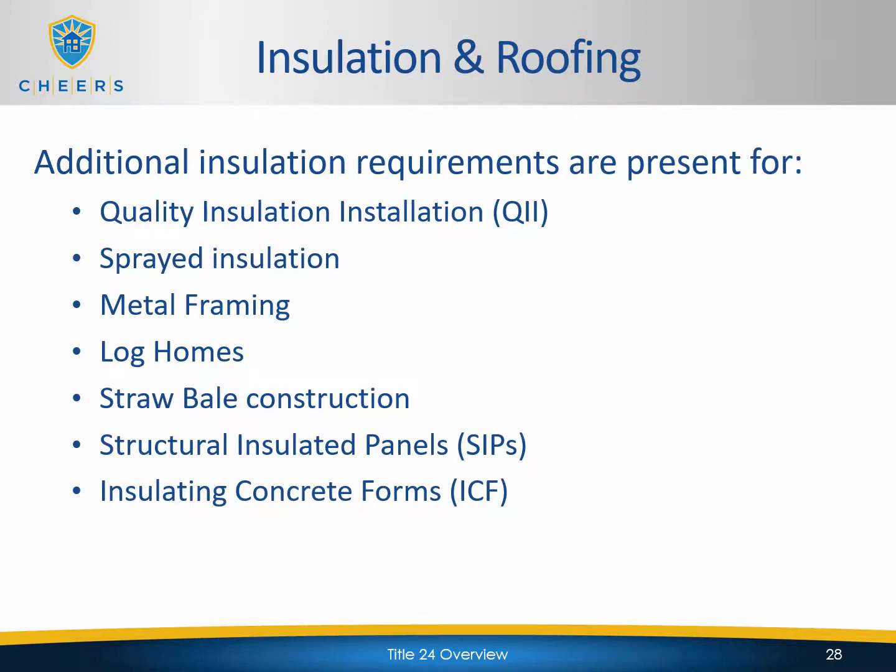There are additional insulation requirements that are present for QII, quality insulation installation, sprayed insulation, metal framing, log homes, straw bale construction, structural insulated panels or SIPs, or insulating concrete forms or ICFs. We're going to be discussing a lot of these additional items in the QII section later on, so you'll hear some of these items again.